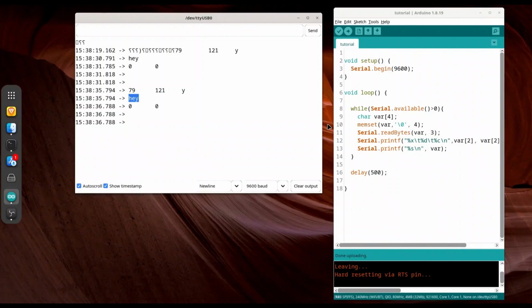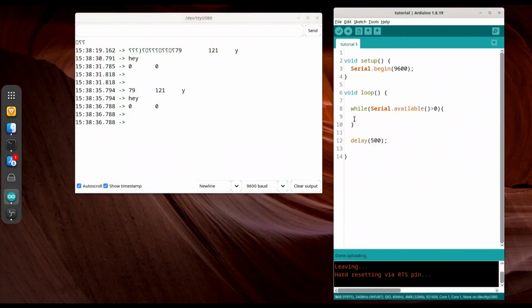Let's say if you send 1, that means that you want to read from the temperature sensor. If you send 2, that means that you want to read from the moisture sensor. And if you send 3, that means that you want to turn some pin on or off. And if you, for example, want to turn on pin number 4, you could send a command that is going to contain only 2 bytes, 2 numbers, 1 and 3, for example. And now I'm going to show you how to use the readString function. I'm going to remove all of this, and I'm going to change this function, let's say, like this. So we are going to have a pause while there is nothing to read.